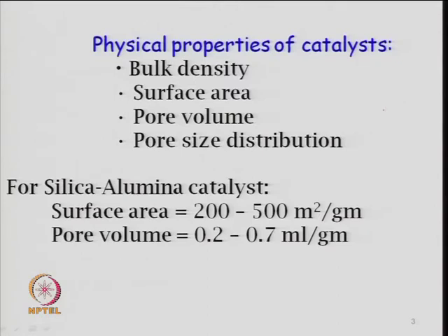If you look at the characterization of the catalyst, or the physicochemical properties of the catalyst which are generally produced or developed during catalyst preparation, this is also a very important issue. There is the bulk density, the density of the pellet, the density of the particle, the density of the powdered material, and when you make a tablet from that, what is the density. So, different kinds of density: solid material, apparent bulk density, and when you put it in the bed, depending upon the shape and size, the bed density. The bulk density is very important when you look at the catalytic property, depending upon the pressure which you have applied when you make the tablet.